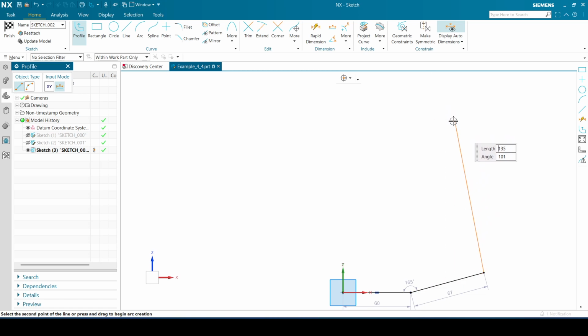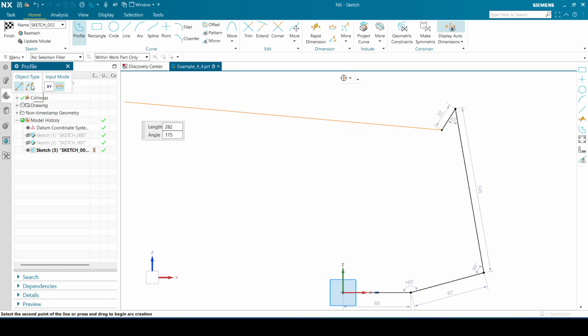You see here it wants to align it with that center of that line. So you can just move it off to the side where there's no constraint indicators and click. Then we have the ear coming down, and then we have the top arc. You can see in the profile tool, if I select arc, usually it will want to go like this, being tangent, or you can just make it come out the top like this. You see here all these golden dotted lines and so on. It wants to add a bunch of constraints. I'm just trying to have it not create any of those constraints.